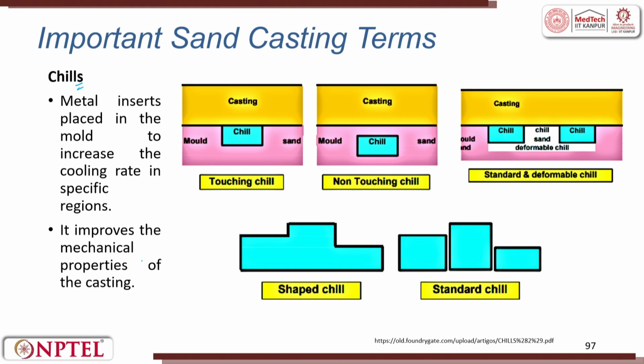It improves the mechanical property of the casting. So, these are all shaped chills, these are all standard chills which are available. Chills are nothing but something like a building block, like your jigsaw puzzle. With this building block, you can join multiple chills together to meet the requirements.